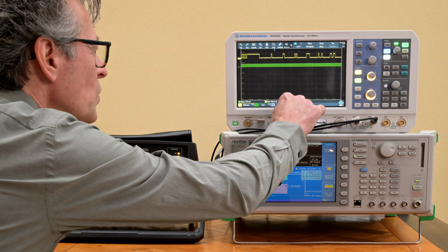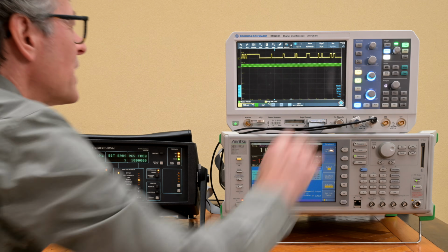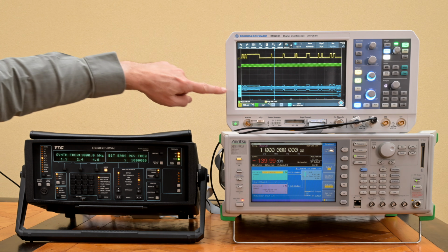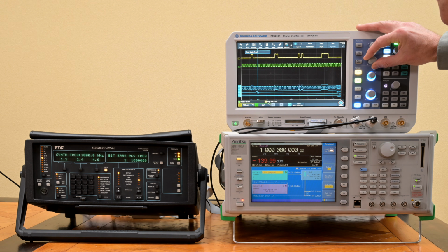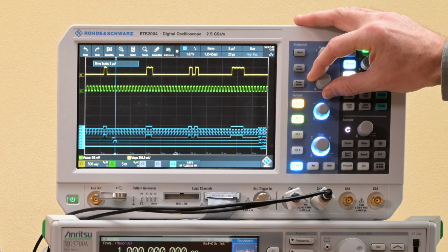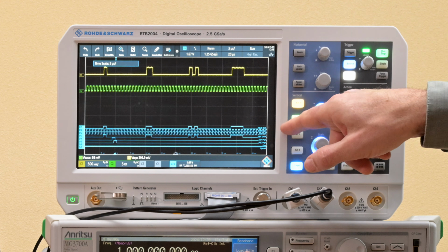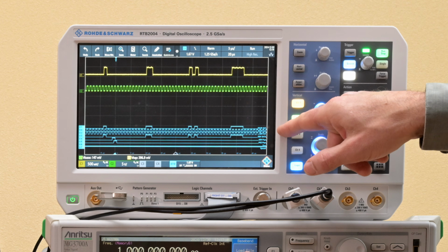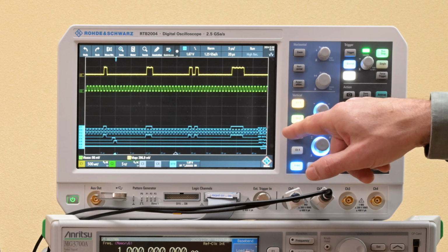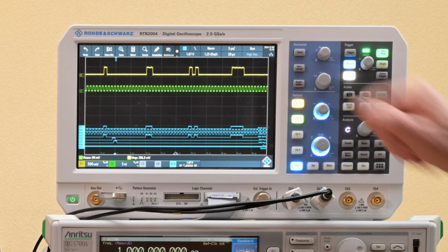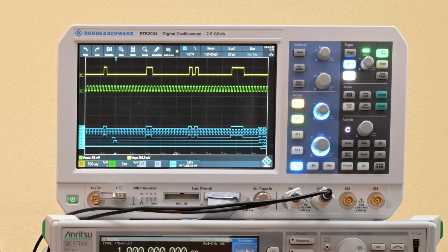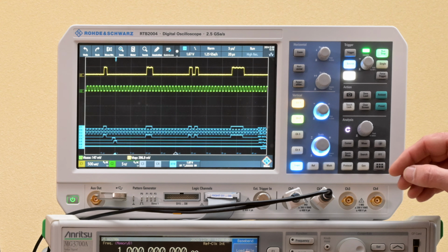So I actually connected a whole set of test pins here to the logic analyzer. Let's turn it on. And we got a whole bunch of test pins here coming into the system. So let's explore them a little bit more, what we got here. Can make them a little bit bigger. We got the receiver data signal, the receiver clock signal, so basically kind of similar to above. We got the generator clock signal and the generator data signal. They are now identical because I've just looped them back into the device, but if you do some real testing, they might of course not be identical, or with external sources, etc.